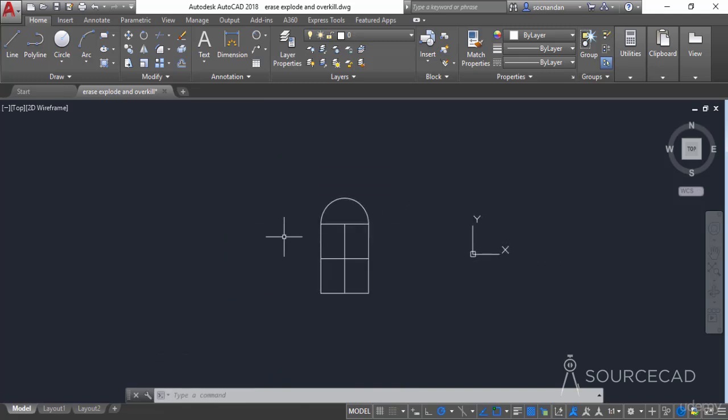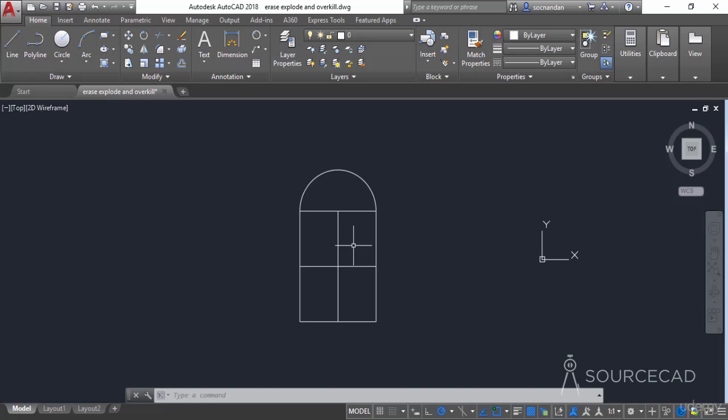When making any drawing, there will be conditions when you'll make some overlapping geometries. For example, in this case, we have the simple geometry which is made with single segments everywhere. But what if we need to make some overlapping geometries? For example, I've selected the line tool, and now I've clicked at this point, and now I need to take reference of that point, so that's why I click there.